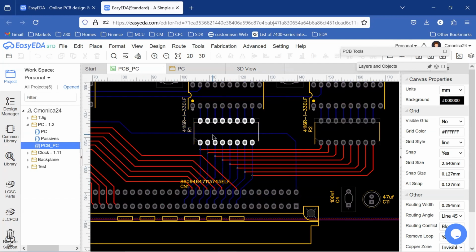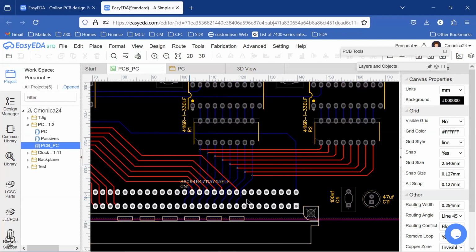So we can see, the 8-bit output goes here, both the high and the low byte go here. But in the memory address register, this will be the low byte from here, and then the high byte will come out here, right? So we will have bits 0 to 7 here, and then 8 through 15 will be here as well.